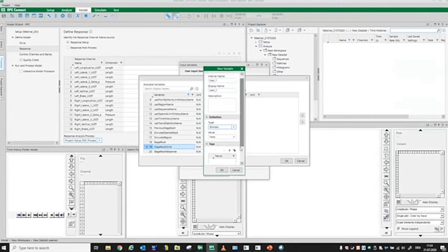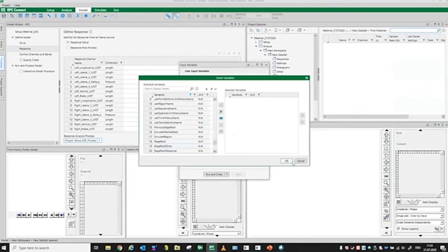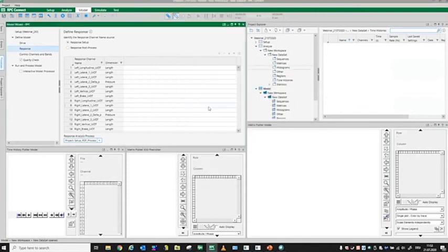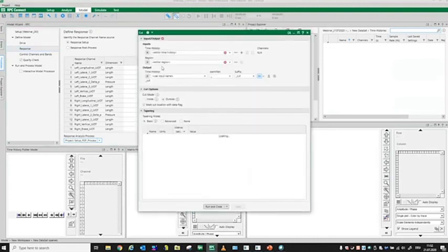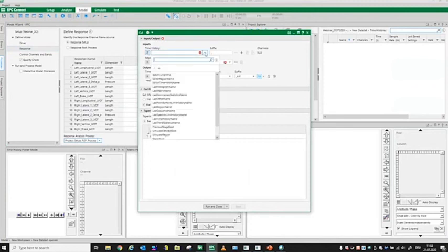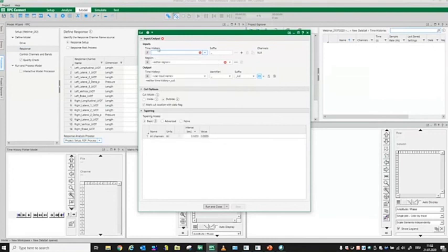And once this is done, you have this variable available everywhere. So if you go into any tools, like let's say we go into the cut tool, as I told you last time in my webinar 1, you can toggle these buttons. So what you can do is toggle here. This is the symbol for variables. Then you scroll down and you see this list, and then you find your file, which I created, and I forgot the name, I'm sorry about that, but here they will pop up and then you can use it right away. So these are the replacements for the wildcards.